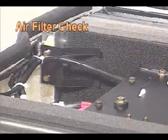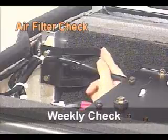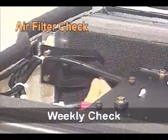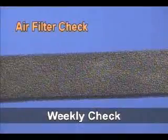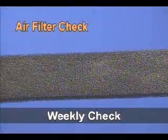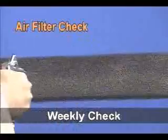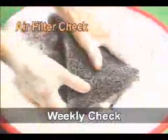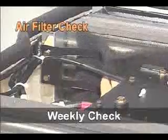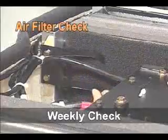The air filter check is the most important one of the periodical checks. It should be cleaned every week. To clean the air filter with compressed air, blow the air in the direction which is reverse of the airflow direction while the air conditioner is working. Then remove dirt with warm water and neutral detergent, and install the air filter after it's dry.